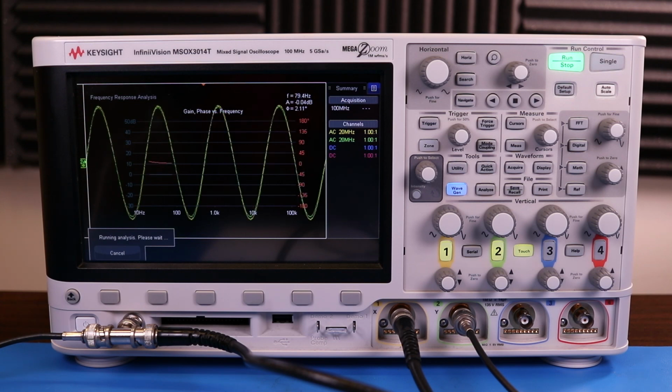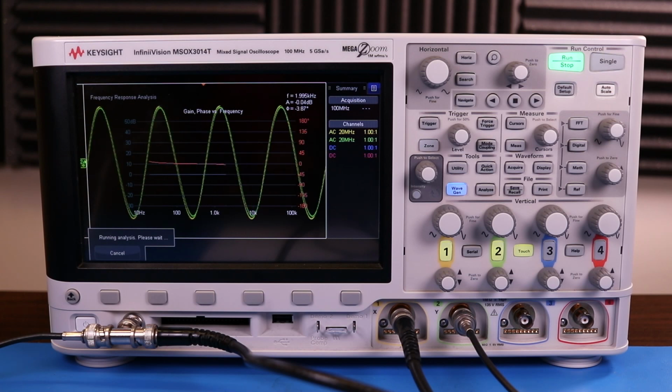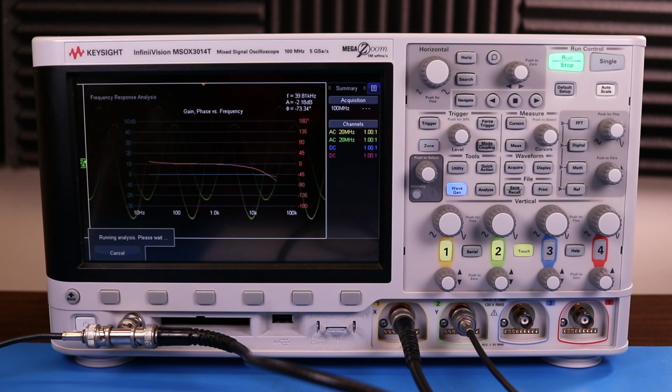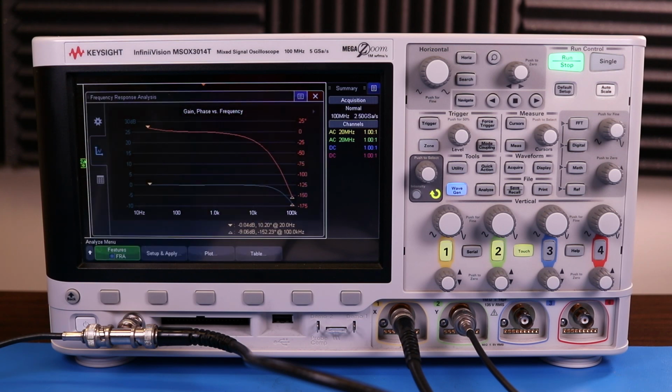You can see from the plot that's developing that this audio mixing console has relatively flat magnitude response and approximately 0 phase response. There is a large deviation once we get past 20 kHz with a greatly different phase response and a roll-off of the amplitude response, but this audio mixing console was only designed to work up to 20 kHz, so this is acceptable performance for it.